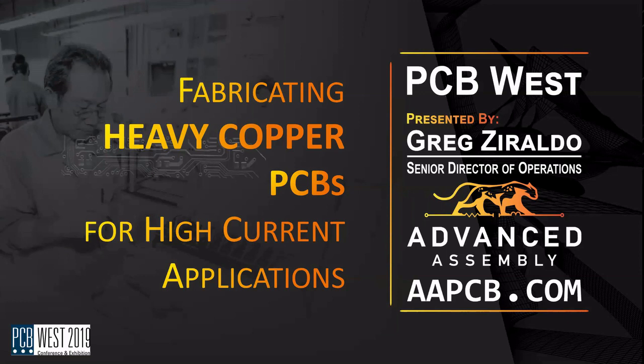The biggest thing with heavy copper from a cost saving standpoint is really making sure that in your stack up, you're able to use as much off the shelf material as you possibly can. Because, like we talked about in the presentation and even just a few minutes ago, if you are using a base material and then plating up or doing a significant amount of plating on the external layers, all of those are more process. They could be more drill cycles.